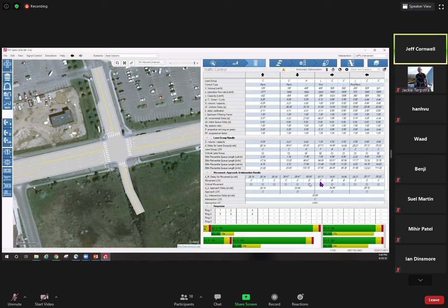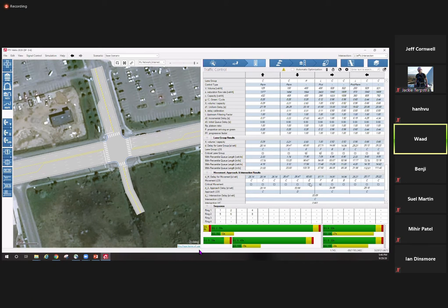Has everybody figured out how to do that? Jeff, what if we are restricted in area? We cannot add additional lanes, so we can change it to be an overlap, right? Correct. That was my next thing I was going to go with. So an overlapping right turn arrow is probably something you only want to put in if you have an exclusive right turn lane